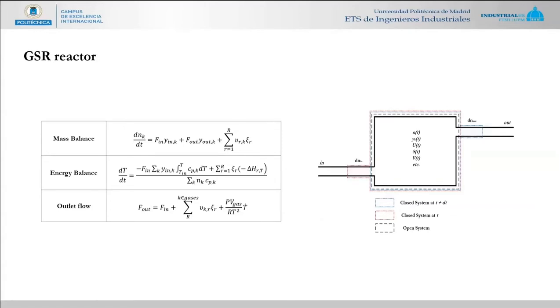As you may know, for ammonia and methanol, there is a preliminary step of generating a syngas stream. This is typically carried out with steam methane reforming units. This is an advanced concept, right, which consists of fluidized beds, which are alternatively exposed to different feeds, right, and have a transient nature operation.